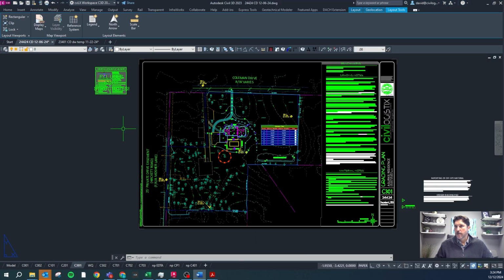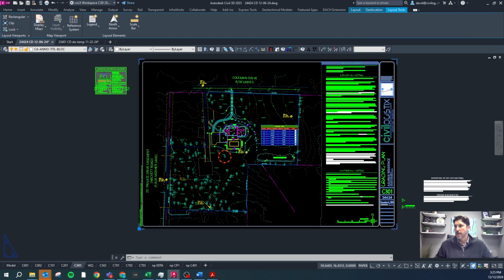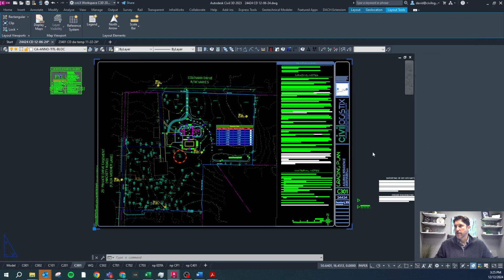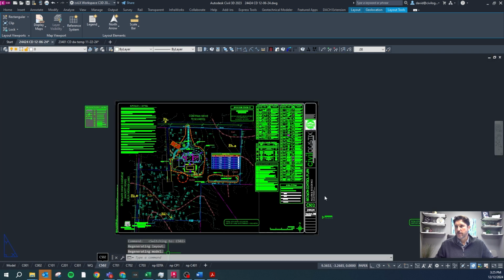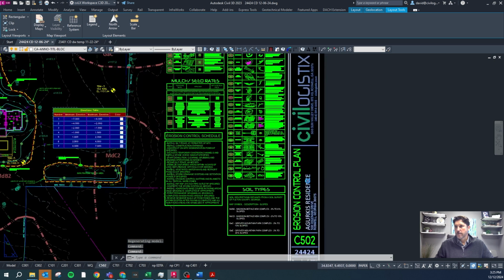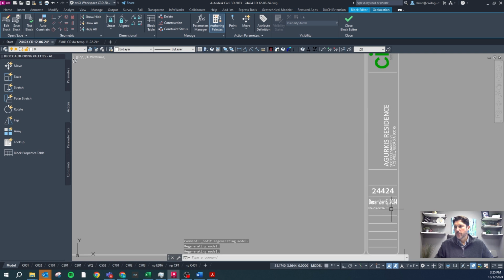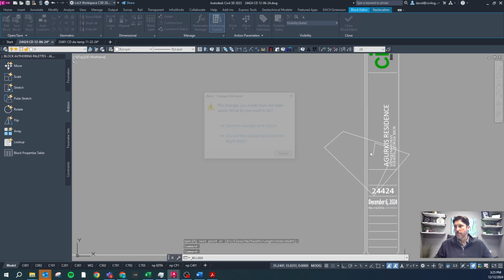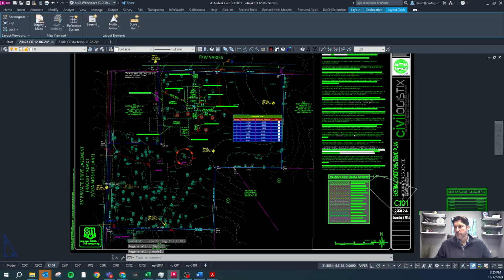Moving on, title block. The title block is a block. The title block name is TB36 by 24. It's the same block on every sheet. This text is unique to this page, so you can change this on each different page, but the block is the same block. So when I change project information or the date on the stamp or anything for that matter in that title block, that now shows up on all of the sheets.